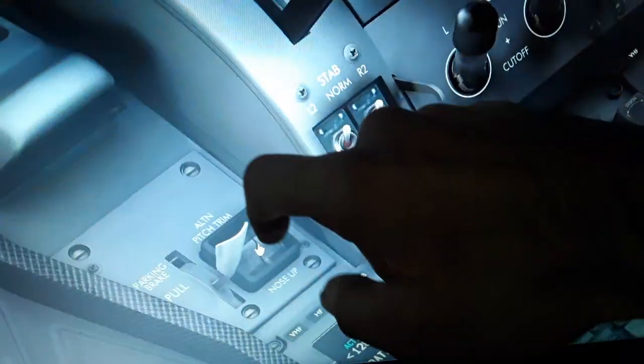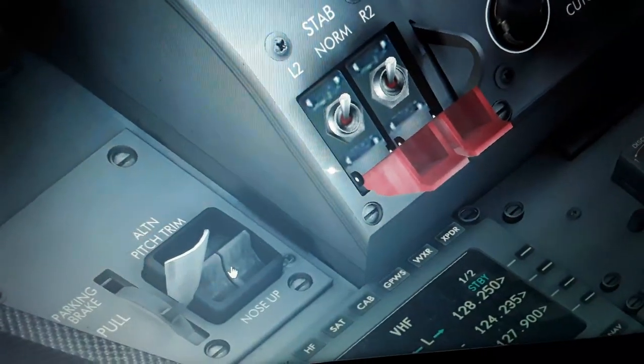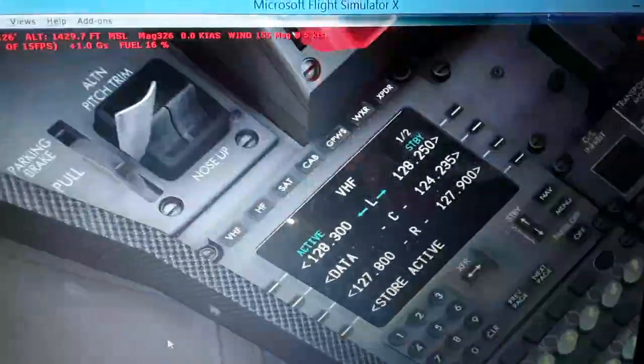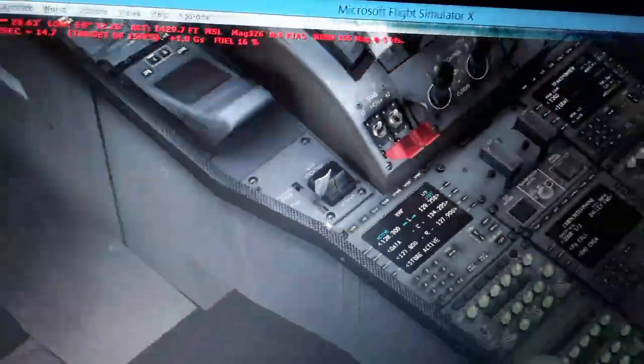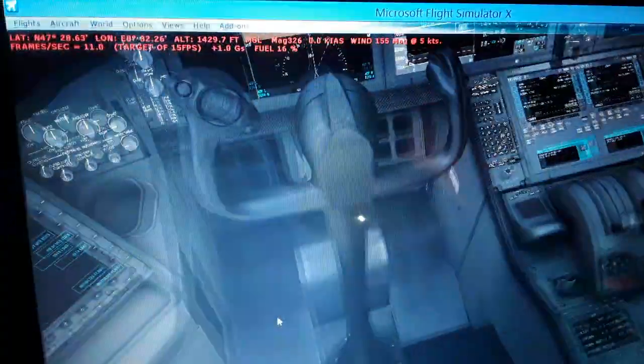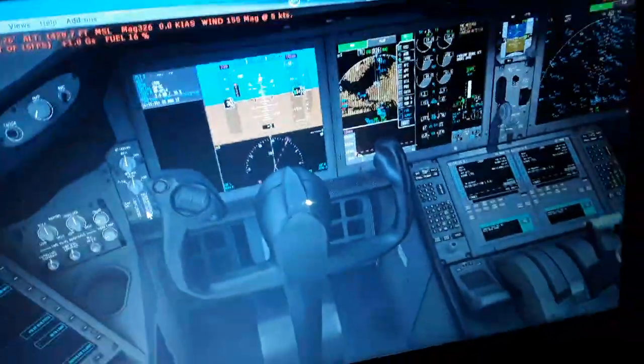So you have only the manual trim switch, the alternate, as you can see, for stabilizing the aircraft in flight. Here and also here you can see the manual trim switch. So you keep trimming the aircraft all the time from the manual trim channel of the flight control.